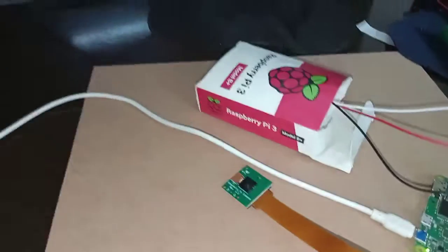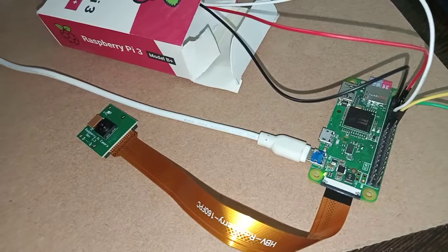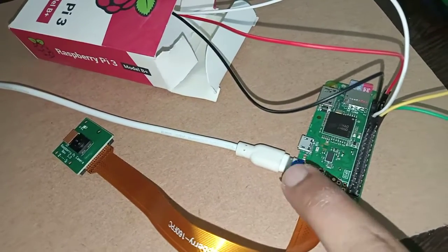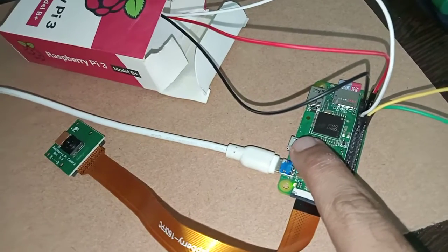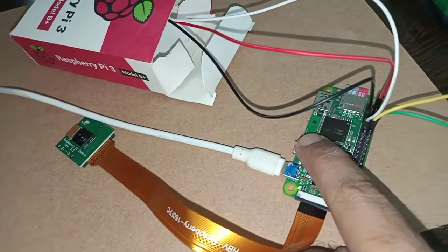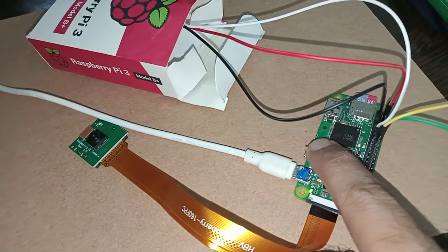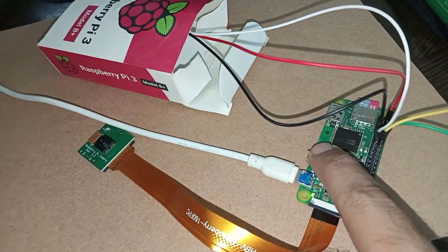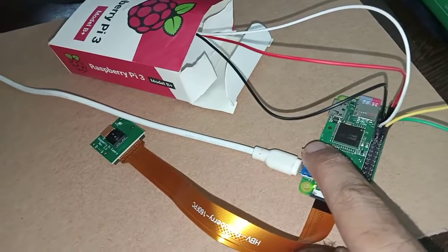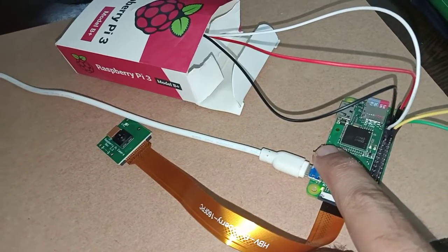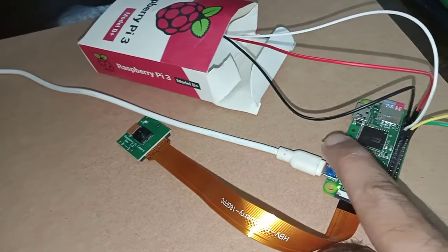In order to start this Raspberry Pi, you should use your mobile phone micro USB adapter, the original charger, and connect it at this particular marked area. Don't connect to this part. This is USB. You can use any micro USB to USB converter and then connect the pen drive in order to download the videos. Remember, you have to connect here, don't connect here. In order to connect any USB device, you have to use a micro USB to USB adapter and connect the USB device to it.